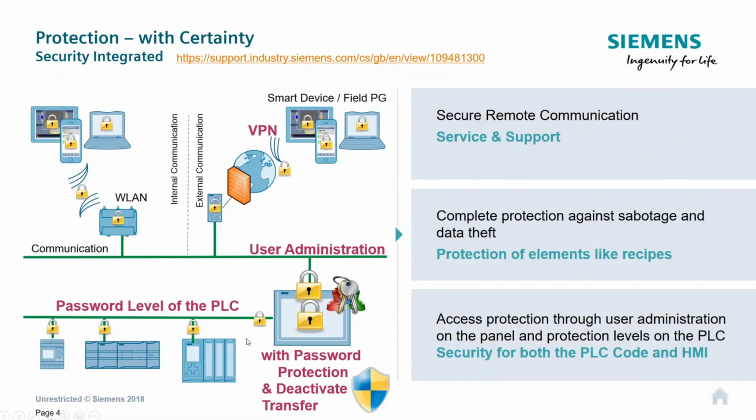The PLCs themselves as well can provide an interaction. So this is great with an integrated project where the HMI actually has to pass a password through to the PLC before it can establish any form of communication. And so this is great to make sure somebody can't come along with an ad hoc HMI and try to gain access to the controllers or manipulate the controllers in any way.